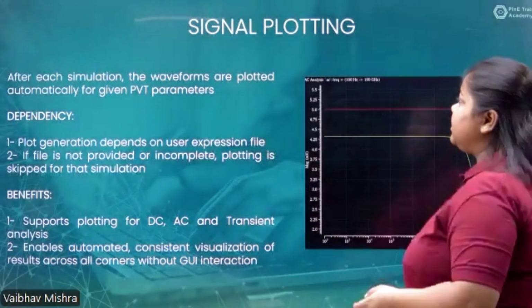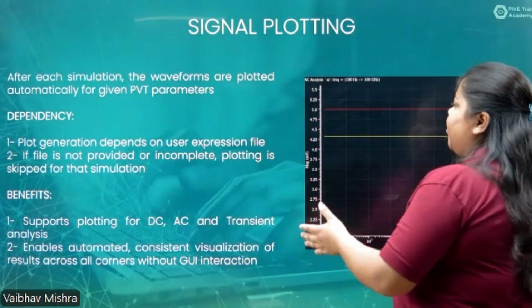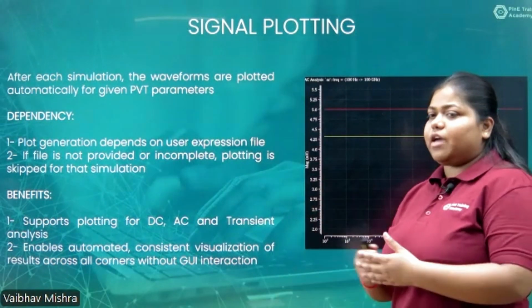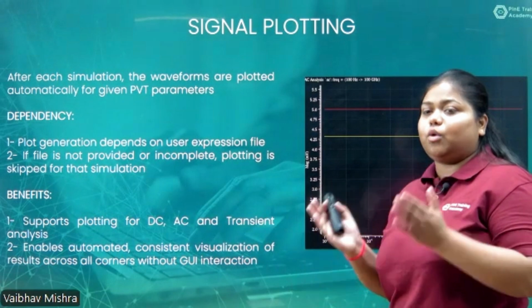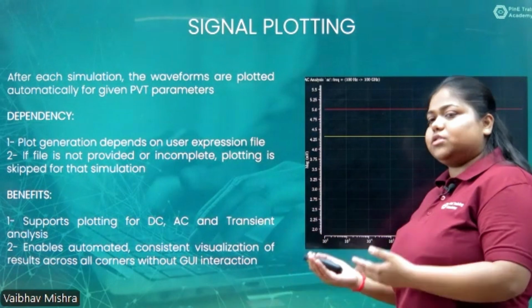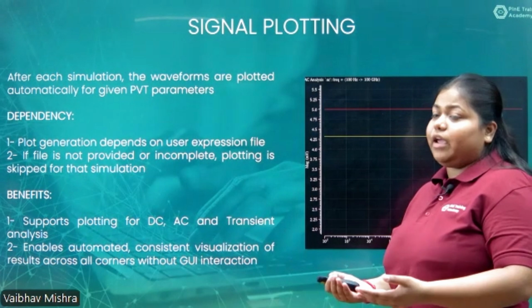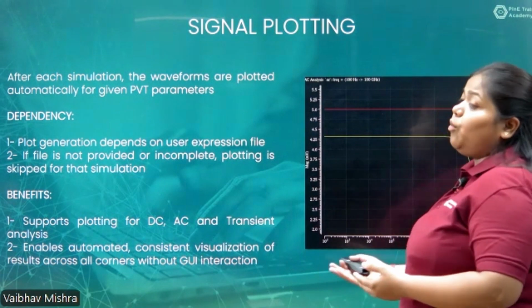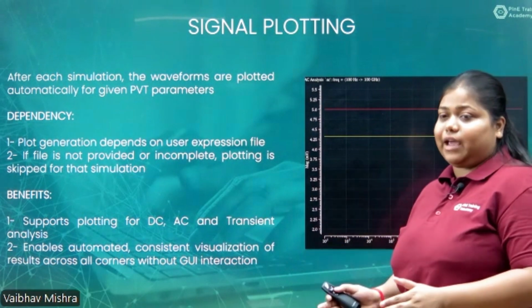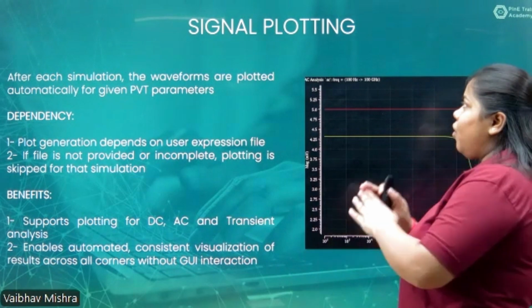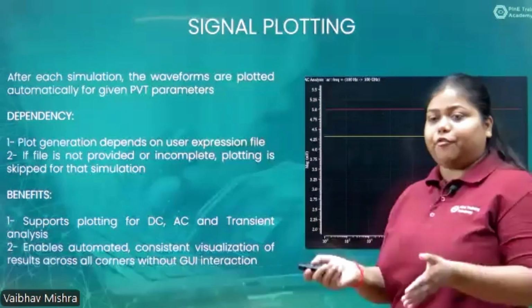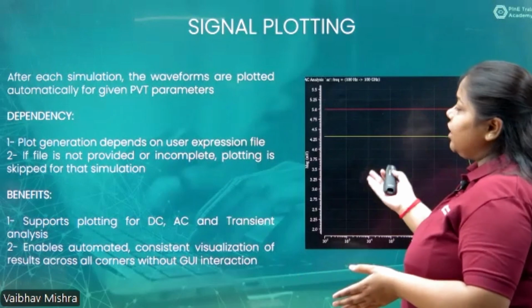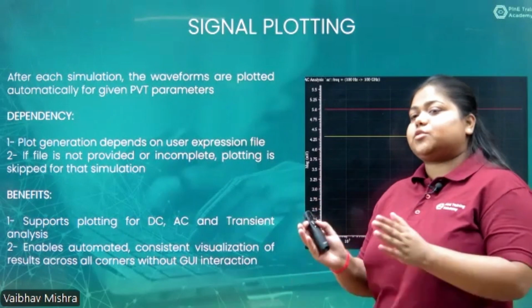So let's move forward. What is signal plotting? In our project, as we have already mentioned, there is no need to open any Cadence Virtuoso. In a similar way, all the signal plotting needs no Viva license. The whole signal plotting will be done through Firefox, and it also depends on the expression file.